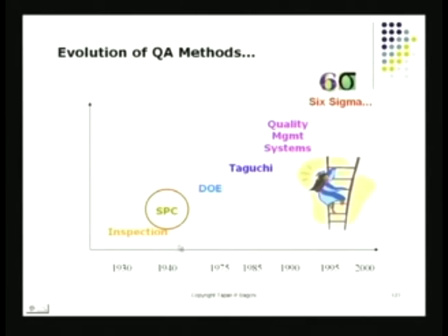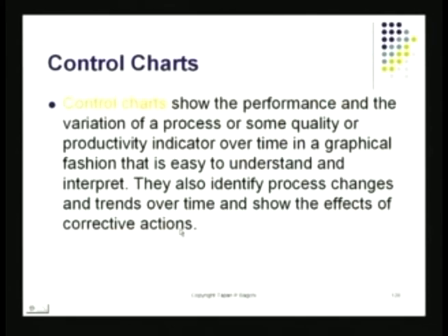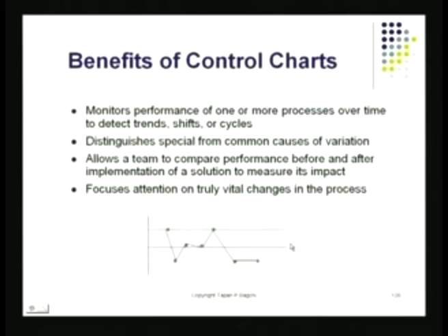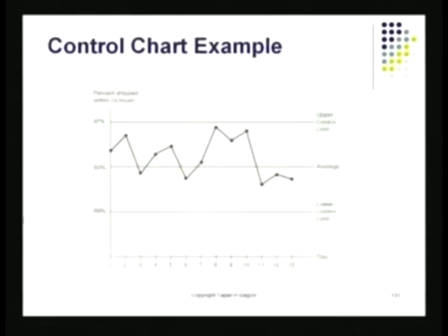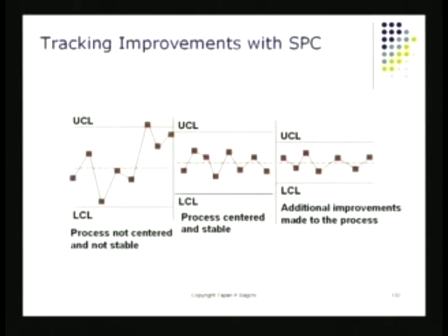So where am I now in regard to my march on quality? I'm right down at SPC when I'm talking about control charts. And control charts are a great way to try to keep a process in control online. Very, very important. And there are certain signals that are provided by the control chart. And if you keep going this way, if you have a control chart that's also partially automated, because automated data collection is possible in many cases, you start with a chart showing a wide variation, initially showing poor precision and also poor accuracy. As you move slowly toward it, your precision may improve and also your accuracy may improve, and you end up with a much, much better process. This is really where you'd like to go.